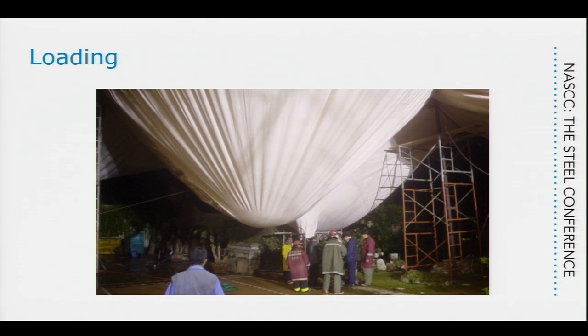But with snow, it's not as easy as with rain. You get some accumulation. So we design it for a certain amount of accumulation, and for the deformation that happens due to that accumulation to not create a divot in the structure, so that it can eventually slosh off.